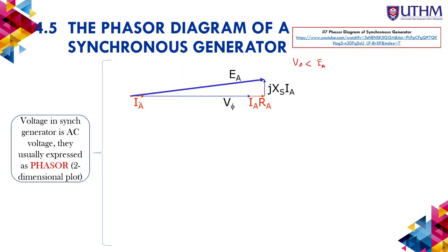Okay, so over here we can see that the IA actually is in phase with the V phase. Okay, so here V phase is the reference, so it becomes 0. So now over here we can see that the IA phase also becomes 0. This means that the PF is actually unity. Okay, so this is the phasor diagram when the power factor is 1.